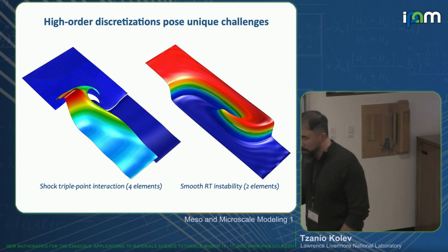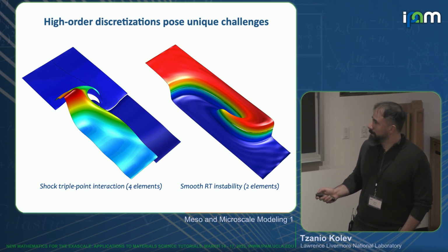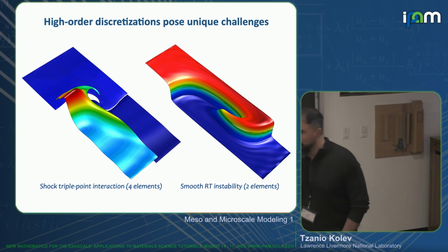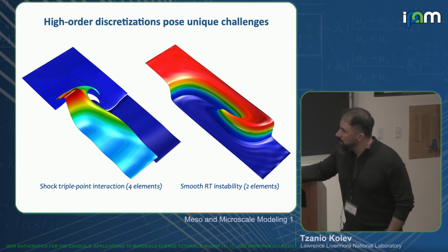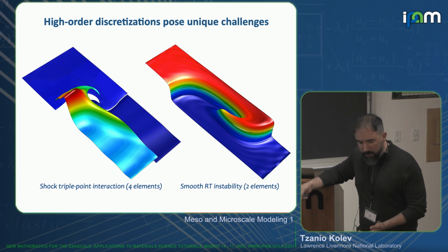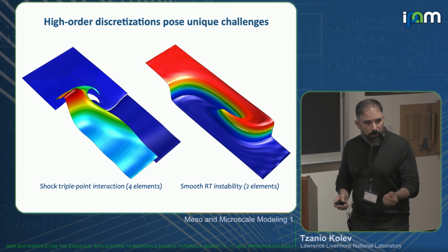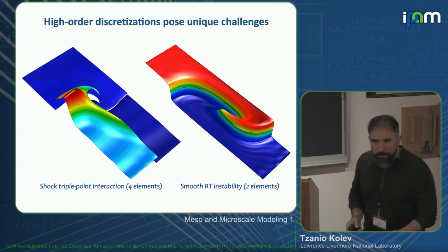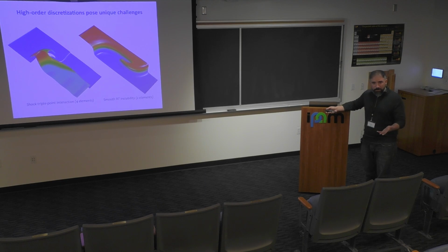This is what a high-order element could look like. This is what a high-order function on a high-order element could look like. You can almost reproduce here a step function on 2 elements. In this case, elements of order 11 and functions of order 12. But you can see that if you have to deal with something like that, if you want to really propagate physics inside the element, you cannot make decisions at an element level. You cannot say this is the element size. Size has to be defined pointwise at the quadrature point level. Right? You cannot say this is the viscosity I'm going to use in this element. It needs to be defined pointwise too.